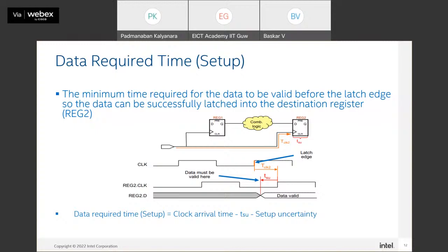That means it can shrink or it can elongate. It won't happen right in the next consecutive clock cycles. In 1 million clock cycles or in 10,000 clock cycles, you can see one clock period may shrink or be elongated. So that is called the jitter. That jitter will also be considered as an uncertainty.